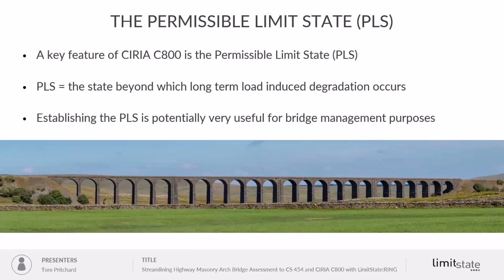Firstly, masonry properties aren't considered in any great detail in the ULS analysis. However, in practice, we know that the properties will start to degrade over time due to things such as environmental effects like scour and brick friability, long-term loading or creep, and especially repeated loading or fatigue. And this needs to be accounted for somehow.